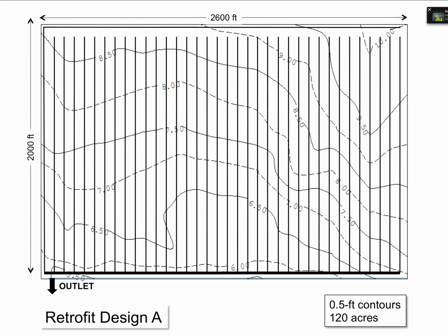So by now you've got something on your paper, and I'm just going to pull up my iPad here and do a little sketching live on this field. So our field elevation at the outlet is 5.5 feet. Let's just say for starters that I want to put a structure right at the outlet located at the 5.5 foot elevation. And so then I'm going to draw that in.